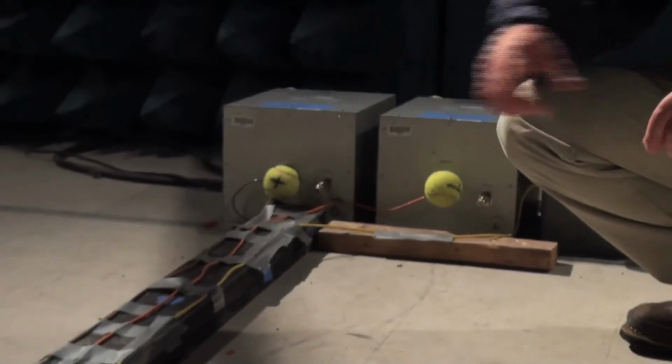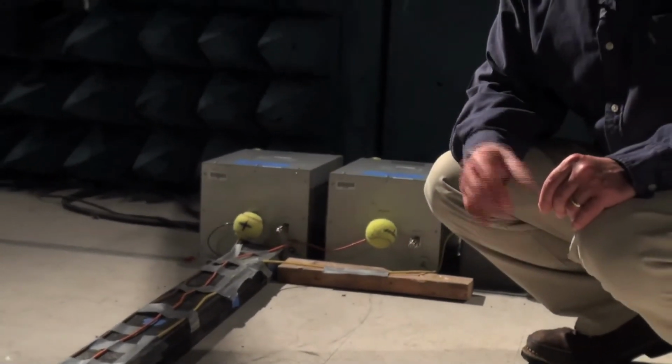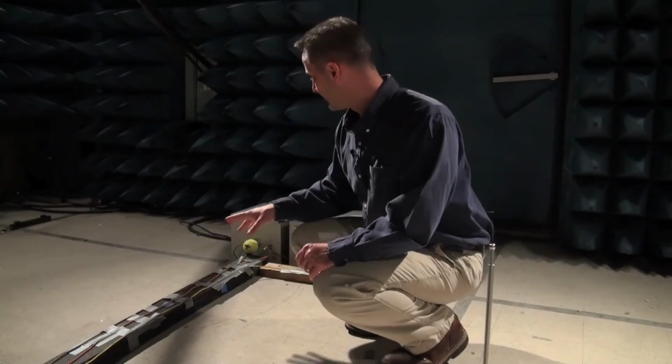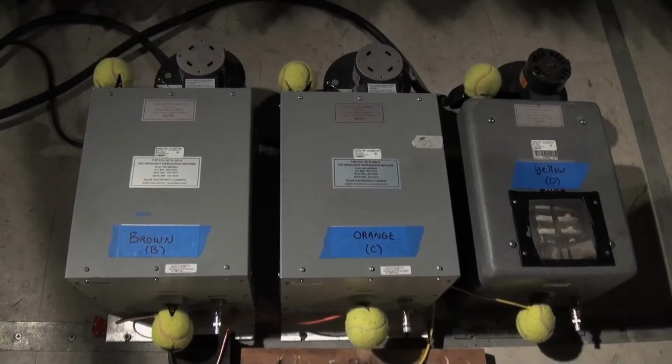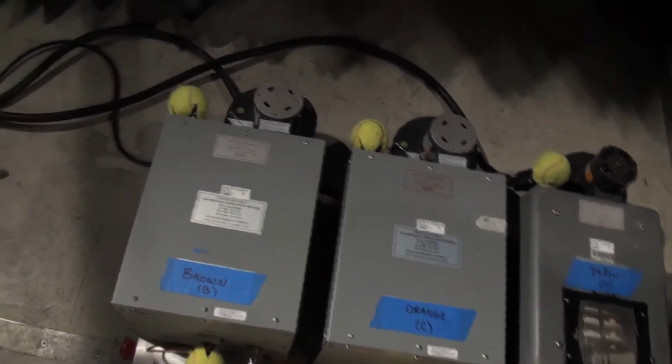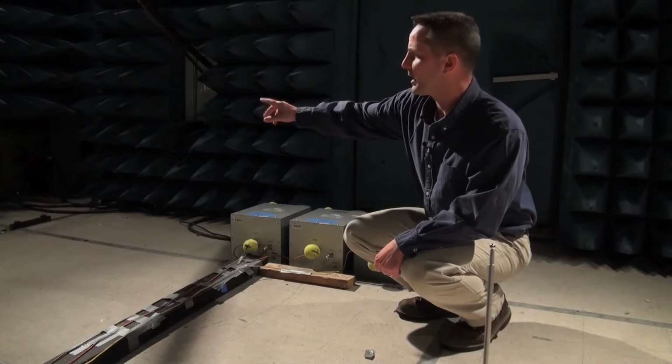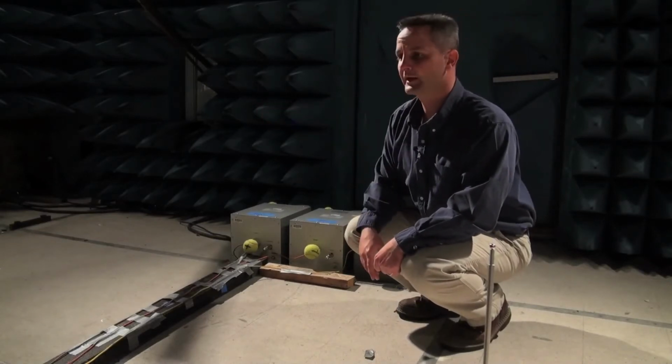So as discussed earlier, the power and signal segregation is, as you see here, on these non-conductive 5 centimeter standoffs. Each cable is separated by at least 2 centimeters as specified by the standard. The power cabling is actually routed to the LISNs that we talked about, line impedance stabilization networks, one for each individual power phase, routed to the back side of the test chamber and cleaned through power line filters which are attached to the side of the chamber.